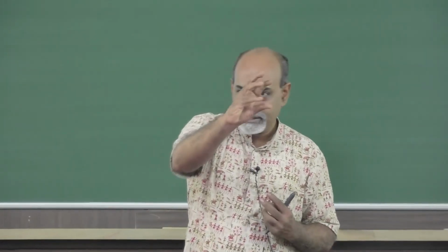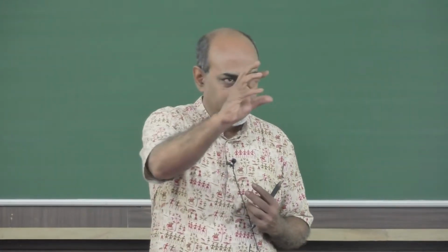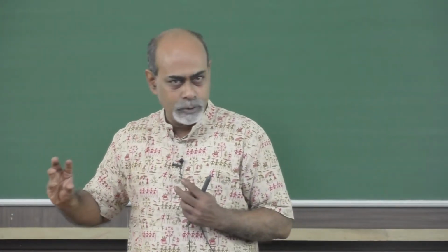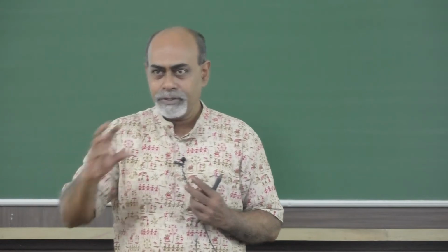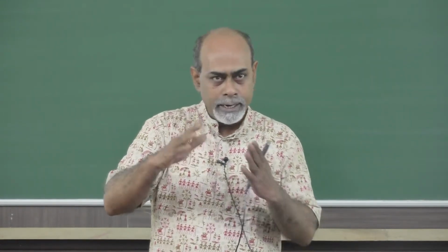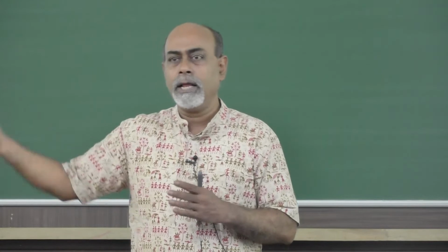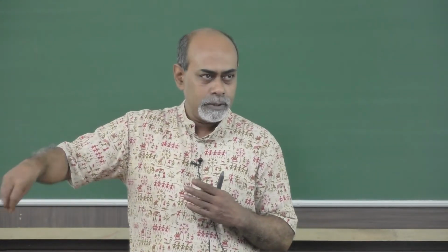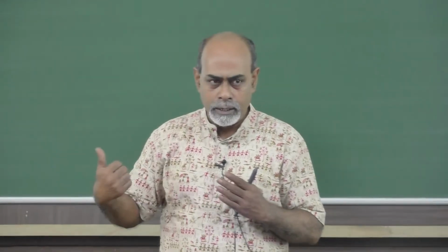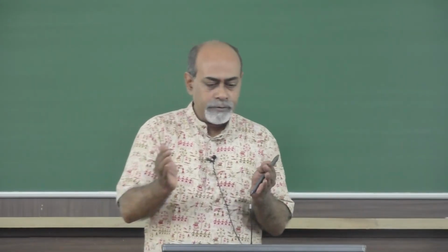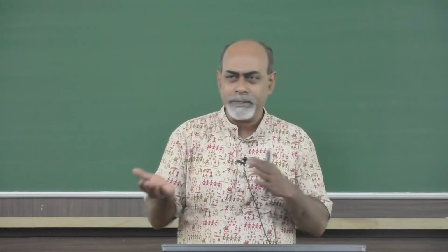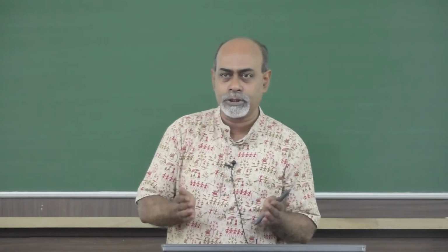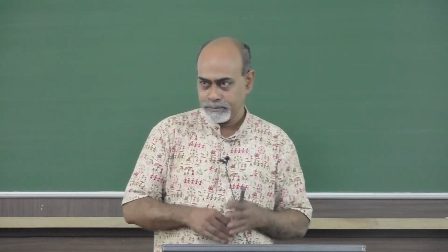So, there is a flux that is emanating radially towards the center, which is emerging from the tooth, and some other tooth on the other side will have the opposite magnetic polarity into which it will flow. So, this is a very interesting phenomenon, because we are having a new, so to speak, secondary magnetic field in addition to the magnetic field caused by the magnet.